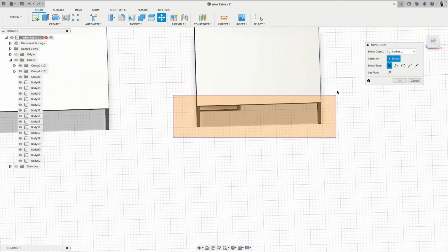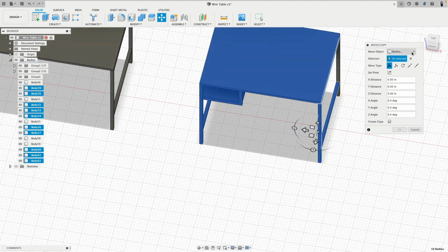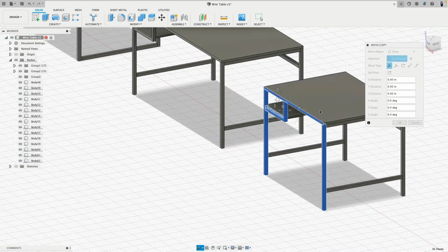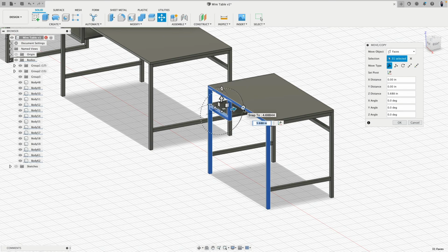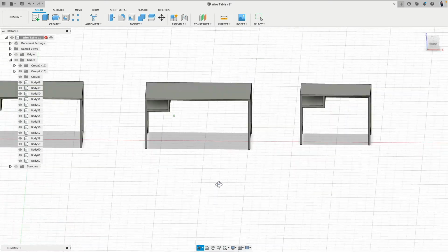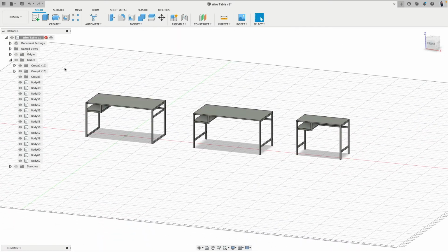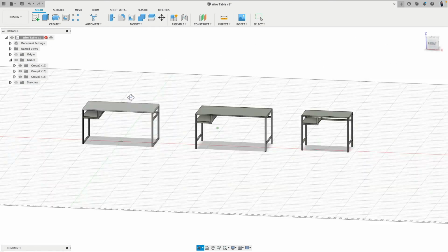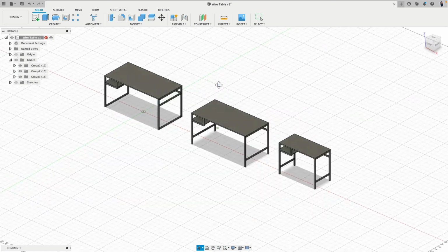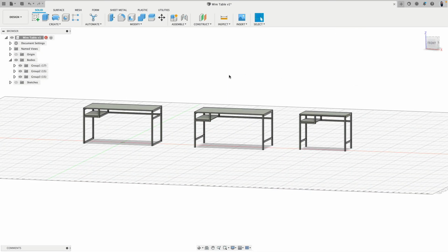But you can't select stuff before in Fusion and then go to the command. We have to go to the command and then select the faces. There we are. And then this goes by 10. There, look at that. So super easy. Cool, no? Yeah, and then we can select all this, put this into another group. And now we are copy and pasting and then moving bodies around, or just actually moving sets of faces around. Literally in no time did we develop variations. Awesome. That's it.